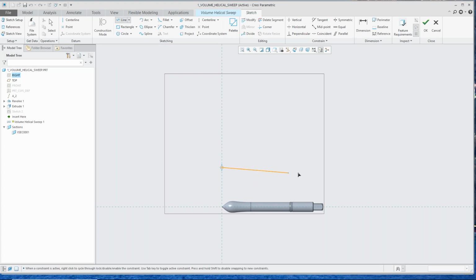Now I could use this as my cutting tool, but what I'm going to do is actually create one from scratch so you can see how that is. But I just wanted to show you that when this geometry removes material, it's different than just moving a profile helically around that, because the grinding wheel is cutting before where the profile would be and also after. So it does create a little different geometry than just your typical 2D profile type of helical cut.